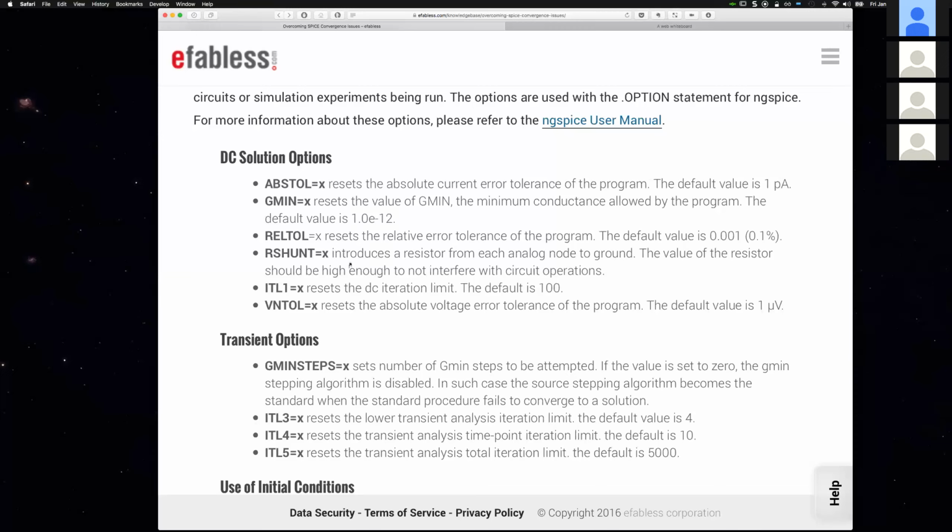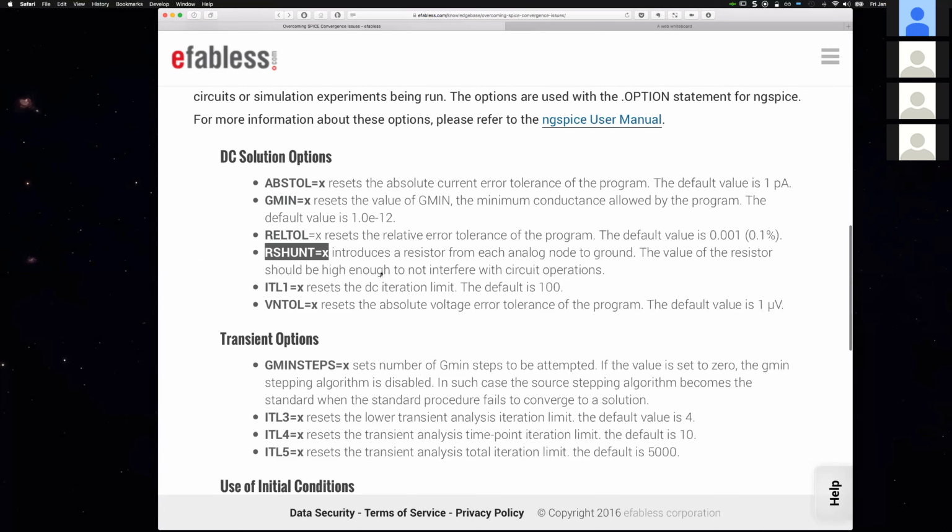So if you don't know the values or the impedances of the nodes you're dealing with, the best way is to adjust it in multiple values and see the sensitivity. In general, you put in a value that is high enough, but it's always important that you understand, either by design or by trying several values, the sensitivity of your original performance to such a parameter.